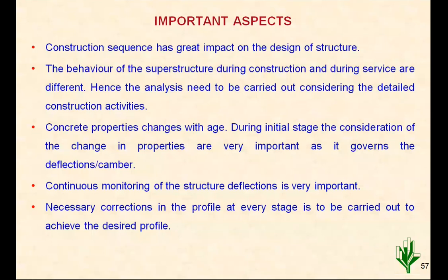It cannot be separated. The behavior of superstructure during construction as well as during service are different, but then analysis needs to be carried out considering the detailed construction activities, and whatever locked-in stresses are there should be carried forward for the service design. In case of, say, cantilever construction of steel trusses, there is no requirement of considering those stresses in service, because after removal of linkage, it will become simply supported again. So redistribution will happen. But in case of cable stayed bridges, that cannot be done.